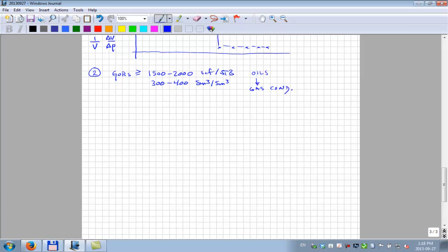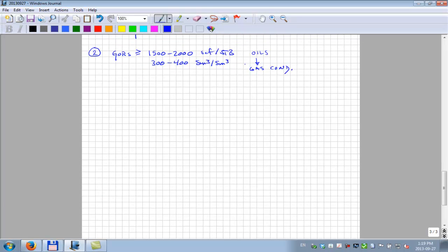general rule. But what happens in these systems is that the fluid itself, as a single phase, even if it's an oil with a bubble point, it's still a very compressible oil. Because there's so much gas in solution in the oil, its compressibility is relatively high. And the result of that is the single phase pressure volume relationship is not a flat straight line, it's kind of a curving upward straight line.